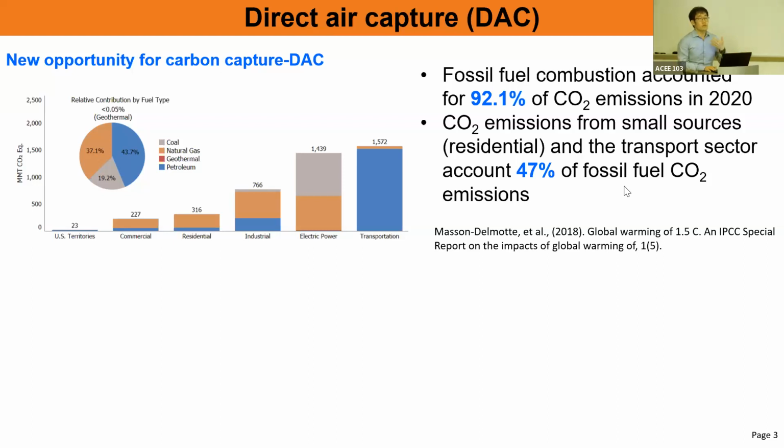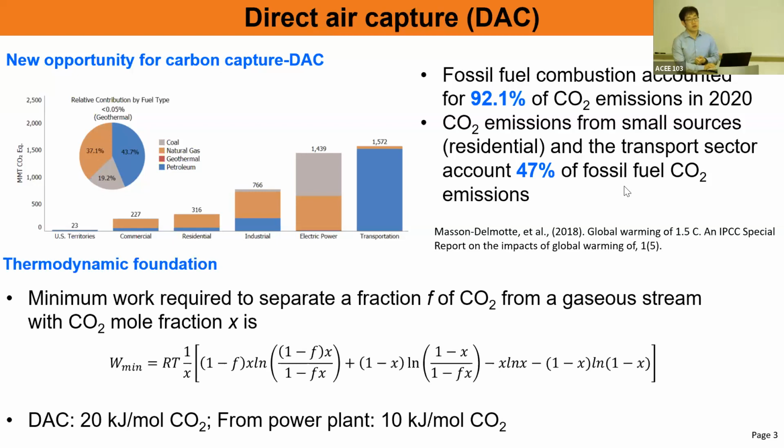So before we do any experiment or research, let's think about whether that's feasible or not, to capture them. There is a thermodynamic calculation of how much energy we need to capture carbon dioxide directly from the air. Here is an equation showing the minimum work that we need to capture them. The comparison is capturing carbon dioxide from a power plant, which needs 10 kilojoule per mole of carbon dioxide captured. If we just move the current technique to the air, theoretically we only need to double this energy.